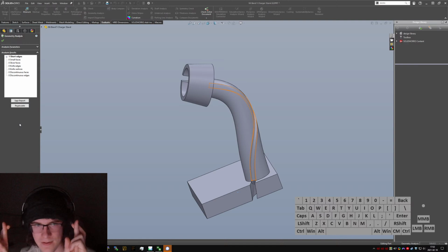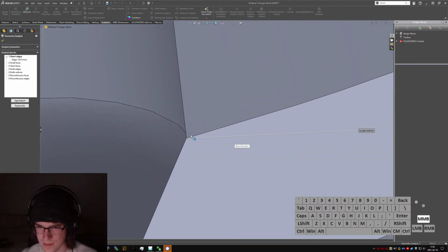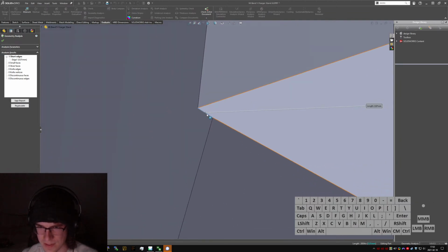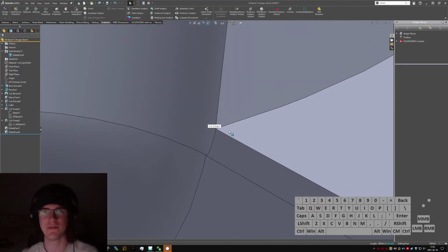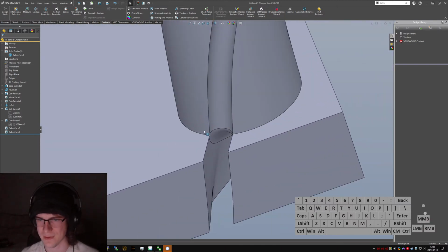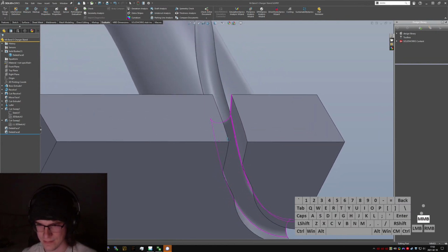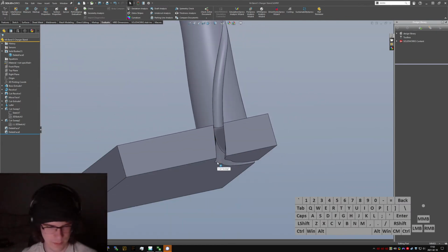Okay, geometry analysis. Fingers crossed, come on. Find nothing. One short edge. One infinitesimally short edge right there. That I can live with. Cool, okay. Now that... Oh, that looks jacked up. I'm just going to cover that with fillets, and nobody will be the wiser.